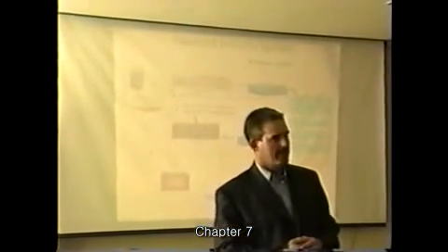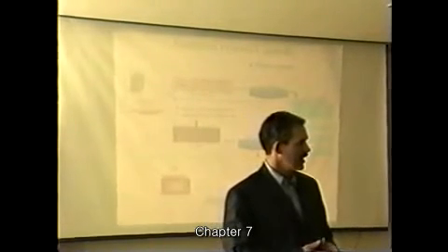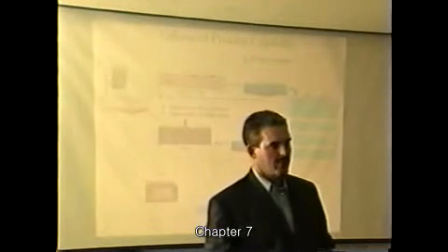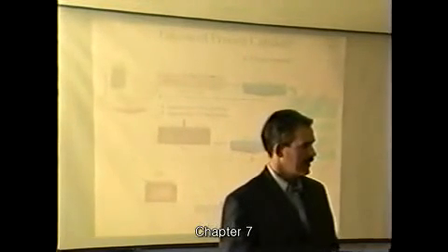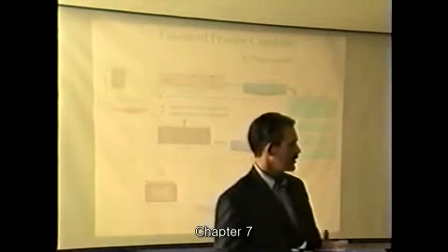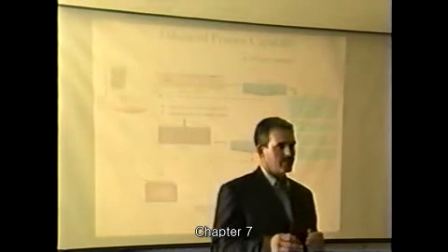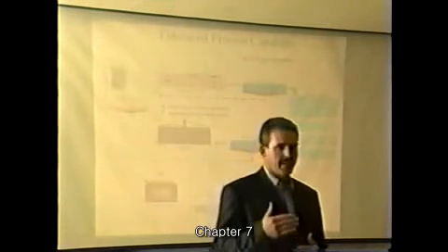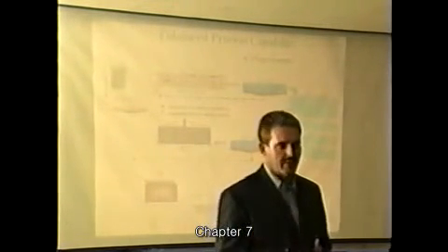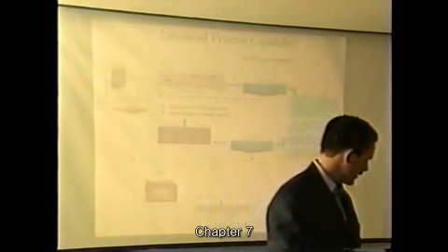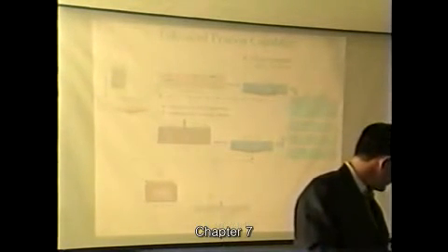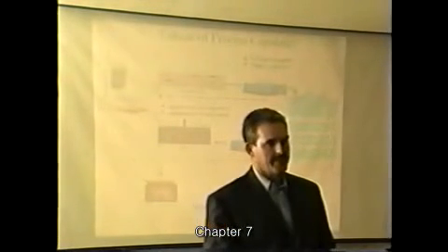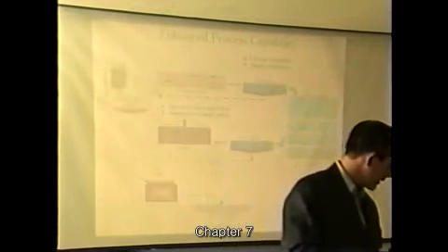We have got a plant which gets coffee effluent. Coffee, as you know, contains a lot of tannins. Tannins are extremely difficult to degrade. Before we went on it, the effluent looked like coffee. With the Archaea, it breaks down the coffee color, and it's actually clear, crystal clear effluent. You are decreasing your sludge production at least 50%.